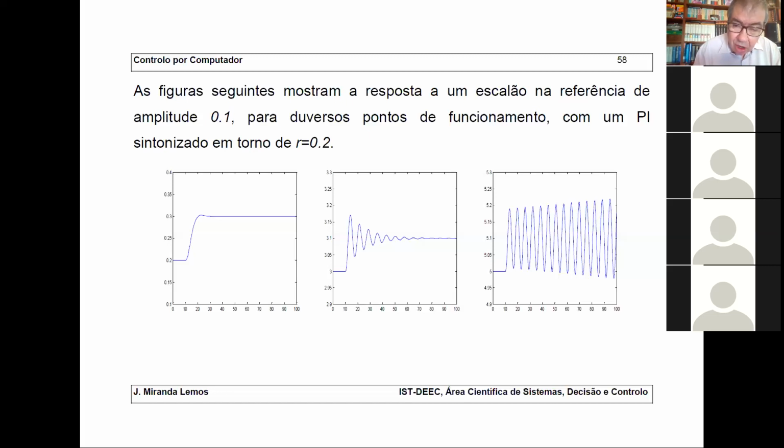Okay? So there is a range for the excess air which is measured by the so-called lambda sensor. And this signal is used by a control system. Now, the dynamics is quite nonlinear. So this control system has a table of gains for the controller that changes the controller gains depending on the conditions in which the car is running.